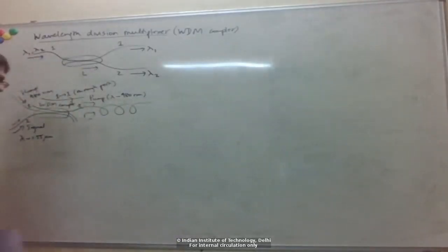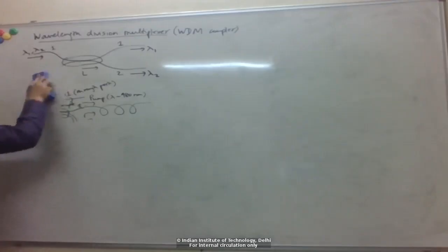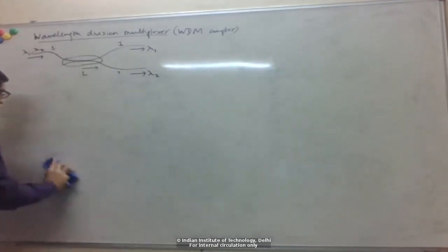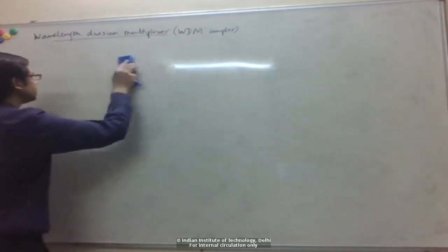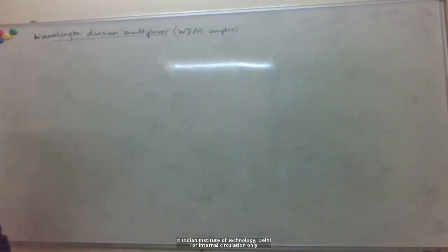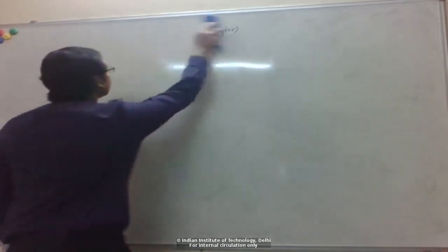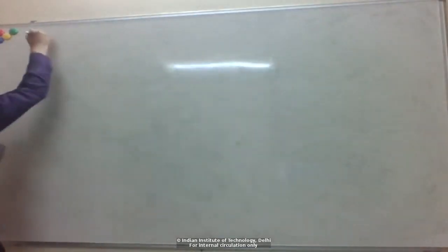So whenever you have any fiber device, like let's say even if you're making some fiber laser or some fiber optic based device, and typically you want some particular polarization to be maintained, then you have to use these fiber polarization controllers, because the fiber itself, because it's cylindrically symmetric, does not have a preferred direction, and because of stresses and non-uniformity, we saw that the polarization gets scrambled. So for many applications where we want a particular polarization to be maintained along the fiber, we need these fiber polarization controllers.